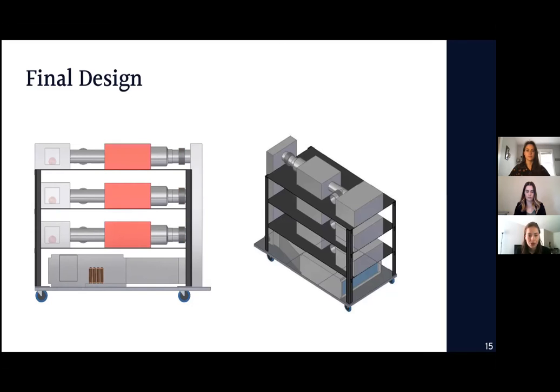After that, it moves through the airflow control boxes. After the airflow control boxes, the ductwork splits into 2 streams. One stream goes directly to the environment. As Emily mentioned, this just gives us greater flexibility of the system and allows us to control the amount of air into the room to a higher degree than the airflow control boxes are capable of on their own.